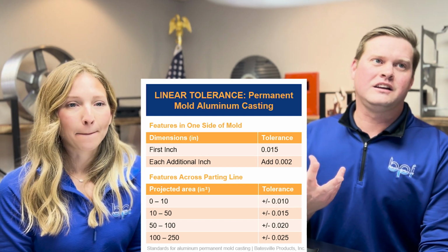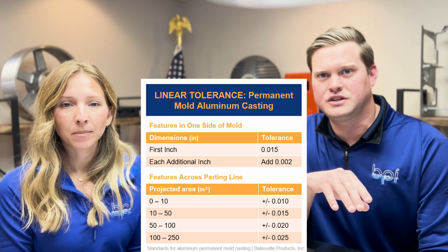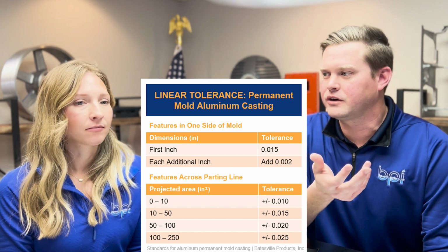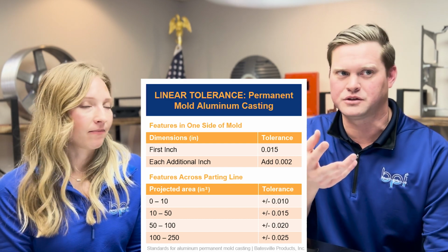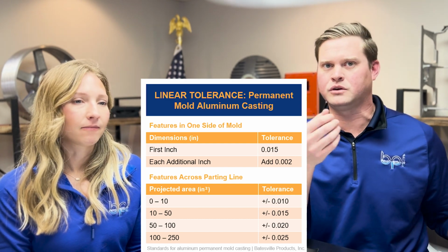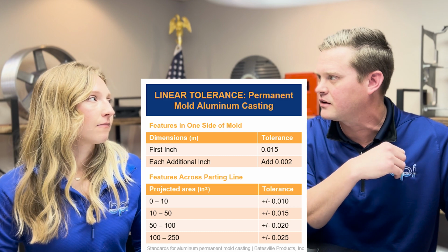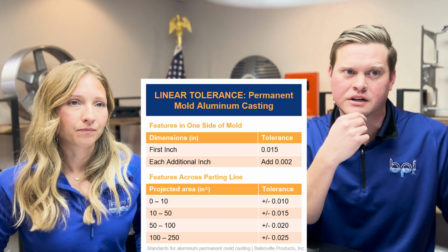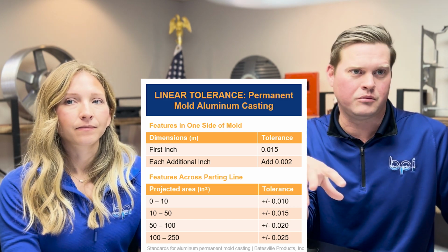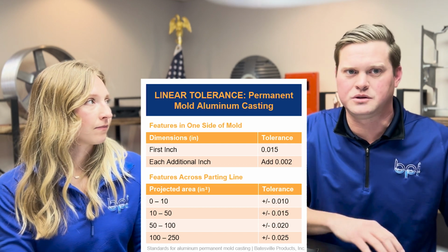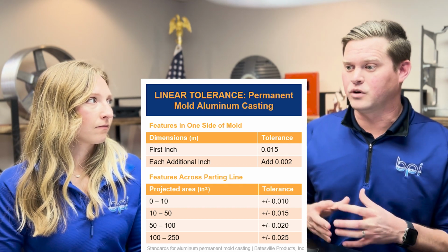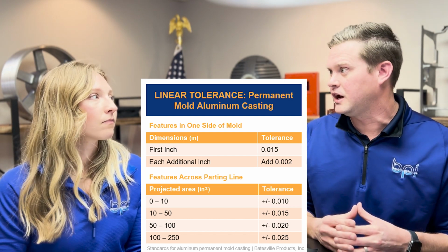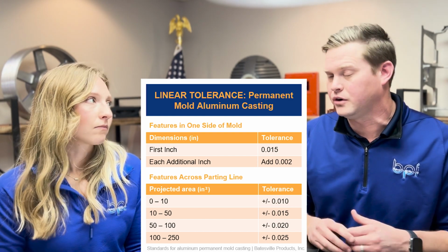Yeah. And again, just in tolerancing in general, if it's not critical, don't over design it. Don't add dimensions that you need to hold in areas that really don't have any impact on the end part or the end application. Yeah. So again, with all this, design it to the process, but design it so that it works for your end goal and not overcomplicating it, adding costs in areas that you really don't need. Yeah.